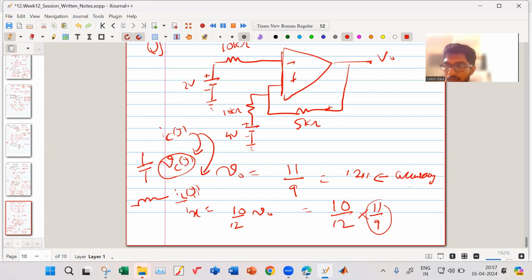Before that, in the steady state, L is short circuited and we have some current flowing. Now if we turn on the switch, current will flow through the second parallel resistor also. But the inductor will not allow sudden changes in current. Yes, correct. Then what is the voltage across both the resistors?